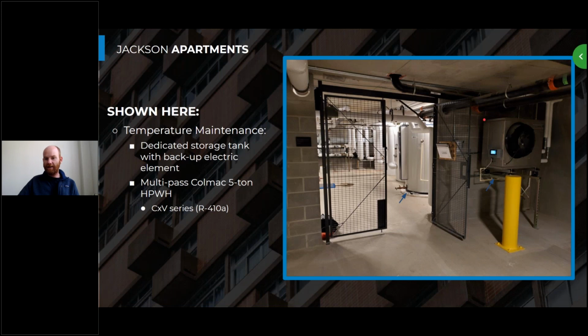Here I said we had a dedicated temperature maintenance storage tank and a dedicated temperature maintenance multi-pass heat pump. So there's our storage tank and there's our heat pump. I apologize for this dark corner here. Sometimes it's hard to get good pictures in mechanical rooms and garages without a good set of lights. This is a CXV. It uses 410A refrigerant, and we located it outside of the room because this fan is on a hinged door.